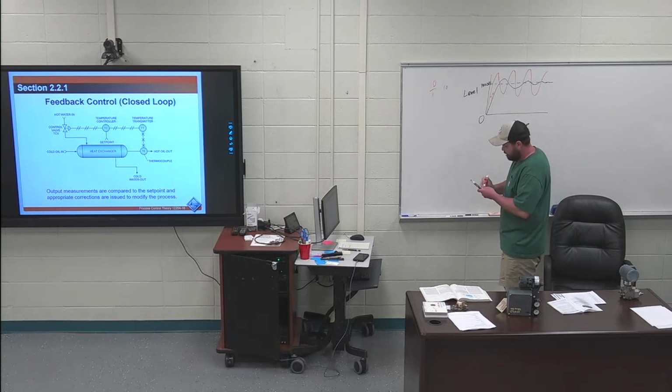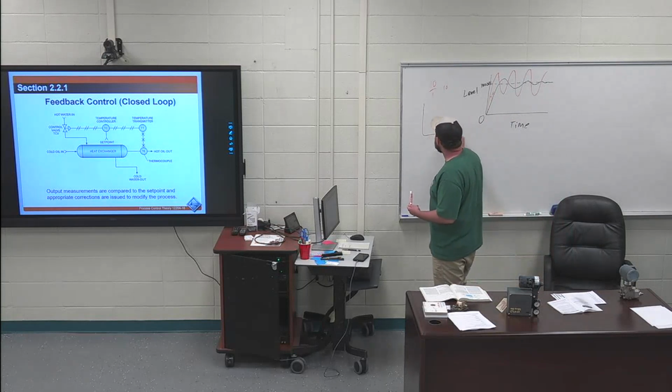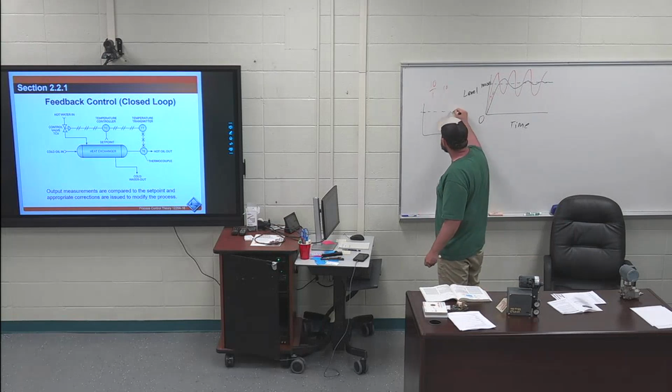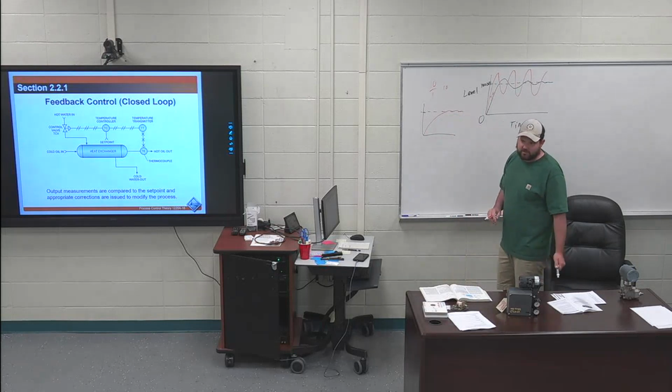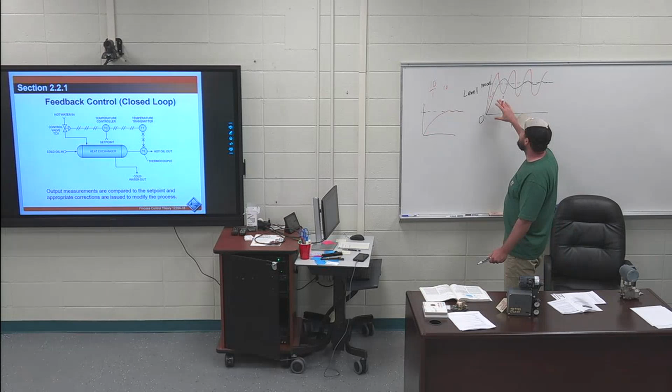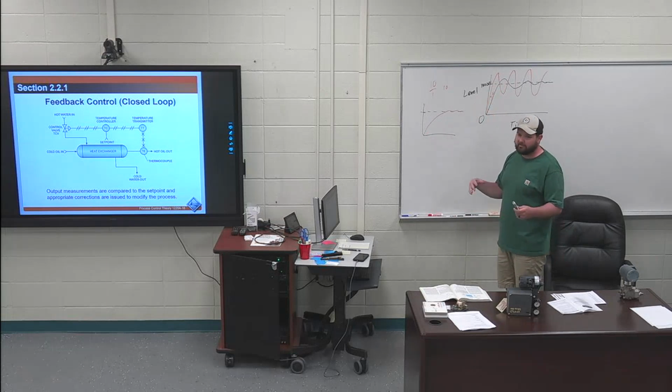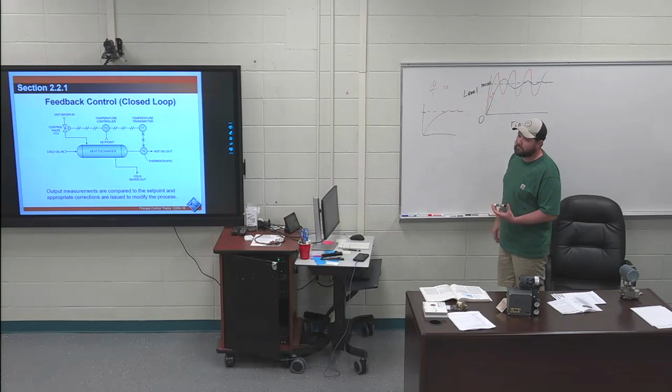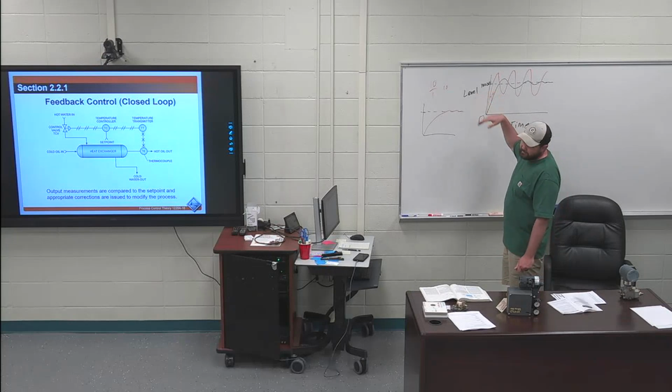Ideally, what I was taught in college, whatever your set point is, say my set point's right here, you want to spend a little bit of time around it, that way you don't have major oscillations. But in some areas you have to get there quicker than others, and then you need much better performance out of your equipment, which means more money. If I had a tank that had to be at 100 gallons, it didn't matter if I was really at 90 or 110 gallons. It's not that big a deal.